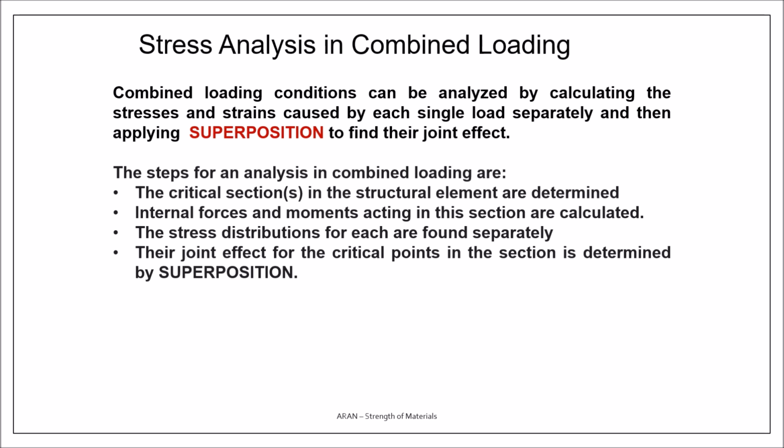In a stress analysis for combined loading, we have the following steps. First, we have to determine the critical sections. Each structural element has an infinite number of sections, so we cannot make our analysis for each section.